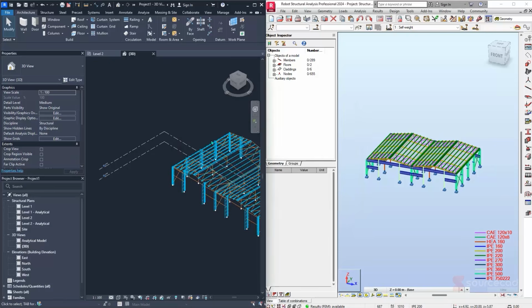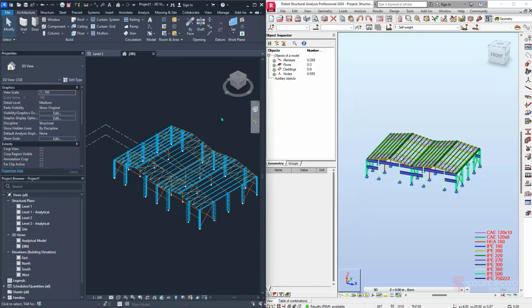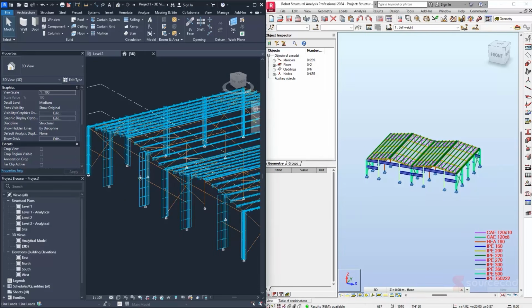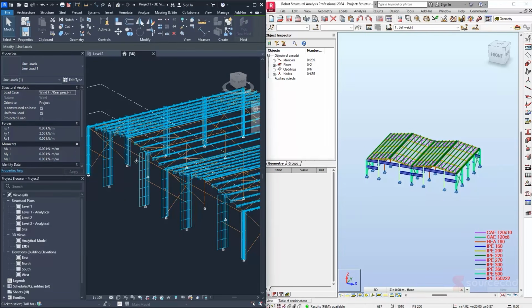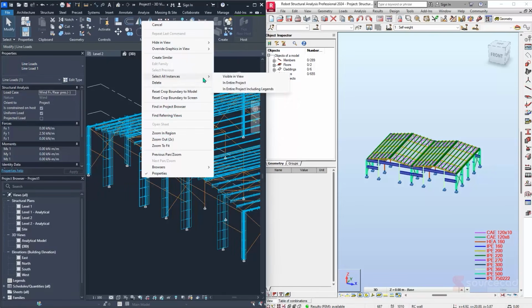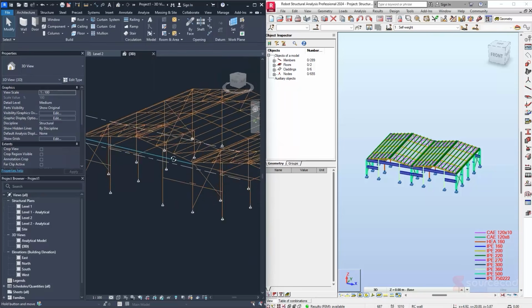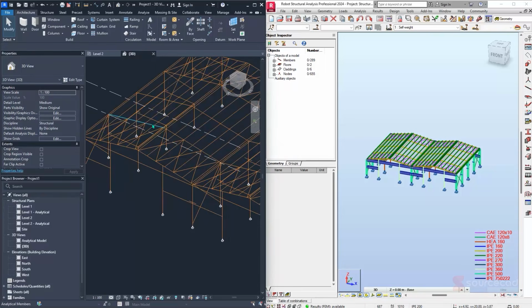That's not an issue. I'll just click on close. But on this other side in Revit, we can clearly see how beautiful it looks. We can clearly see that these are just our loads. These are wind loads being shown. If I don't want to see them, I'll right click, then hide in view, element by category. So this is how our members look.